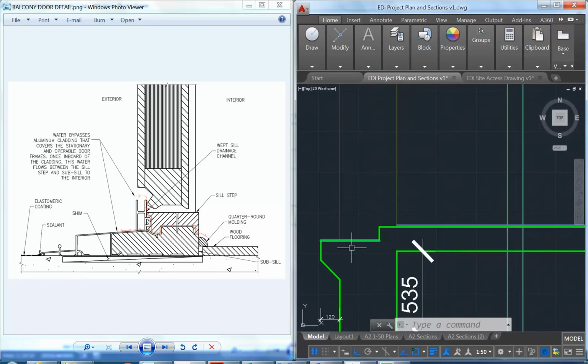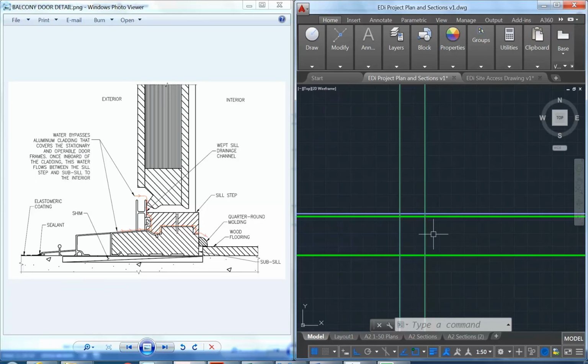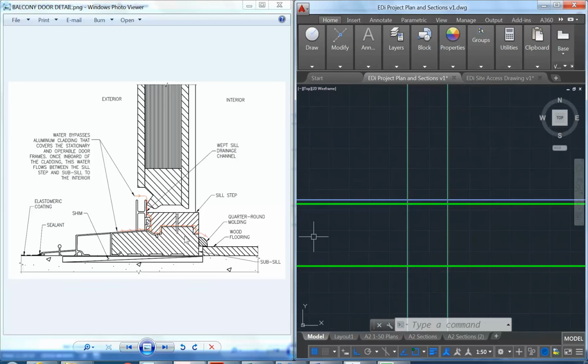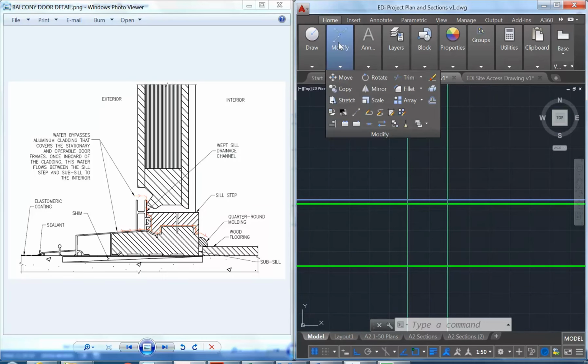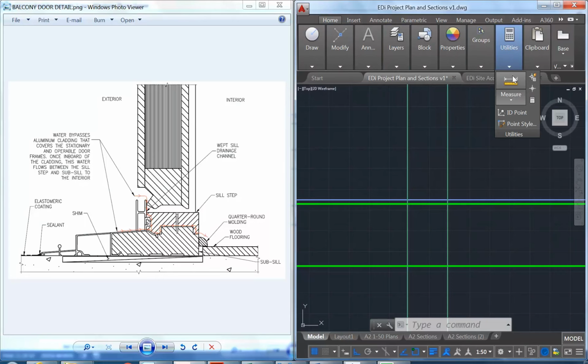And then you can see here, again, just reminding you, we're going to have to work out some sort of balustrade detail for the edge here, but that's not the detail we're focusing on. The detail we'll start with is the threshold that you can see here. And so we may need to make some allowance for the depth of the door. It may be deeper than the wall thickness that's been allowed for there. So I'm just going to measure that.